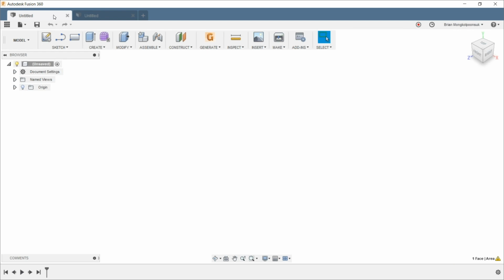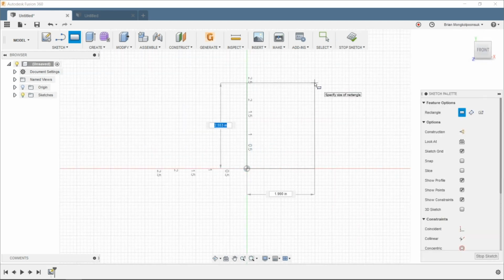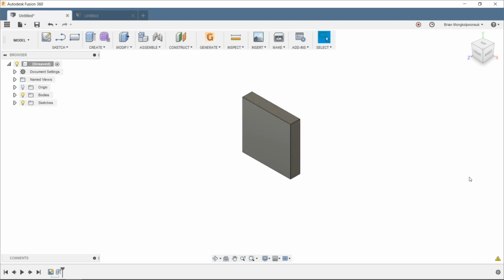So first, usually when people model inside of Fusion, assembly or not assembly, they would go straight to the sketches, which I have done in the past as well, and maybe sometimes still do. But you would create your sketch, extrude it to become a body, and then they think, okay, now I need to create another body because I have multiple bodies, or components, what we call in Fusion, in my design here. So I'm going to have to create another one.